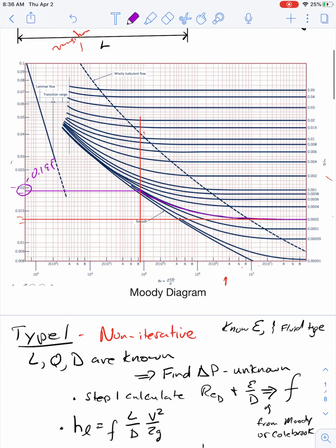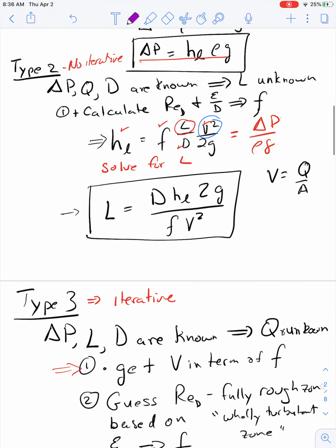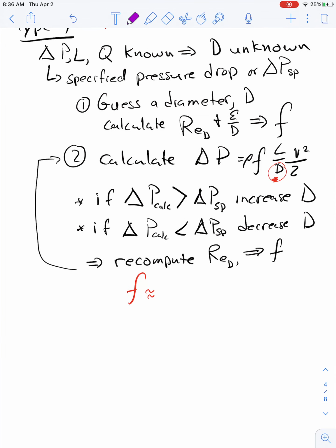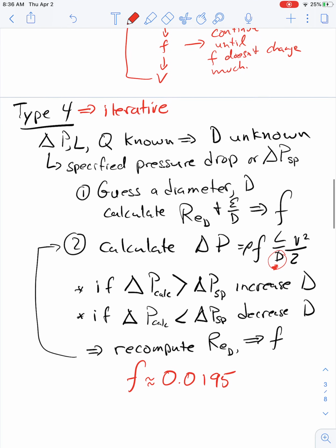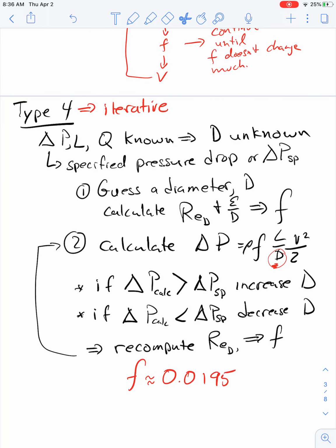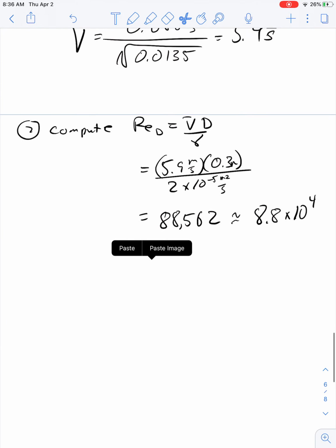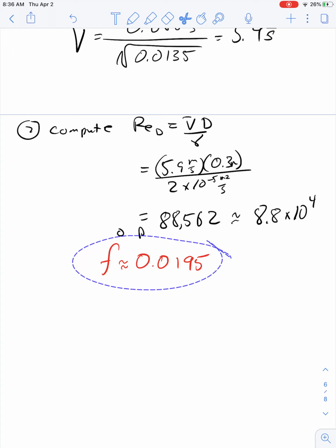It's obviously not perfect. Sorry. 0.0195, right, just through that. So we'll come back down. We have 0.0195 for our new friction factor. Copy that. Back down to our problem. Okay, so here we have the friction factor, and we got that again from Moody.